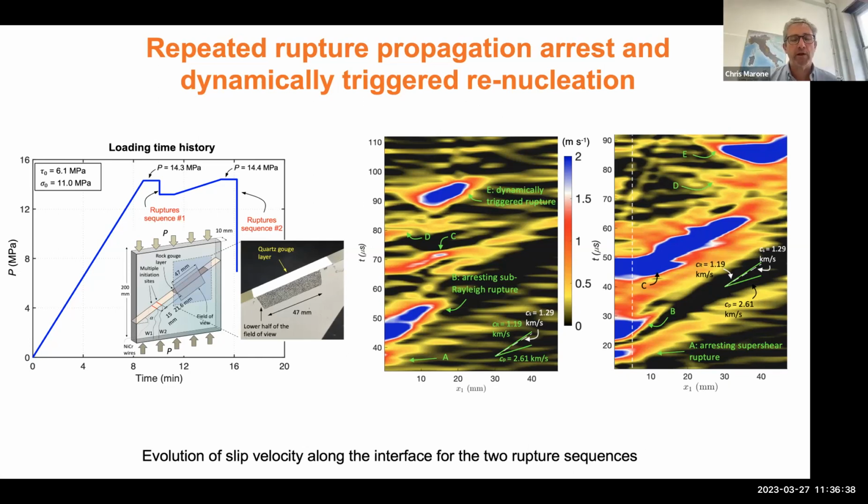Yeah, and maybe that only happens for these more dynamically propagating cases. I don't know, because indeed the dynamic component is a key part in here. If the normal stress does not change rapidly enough, then the shear stress follows, and the Prakash-Clifton evolution does not come into play. So there is an interplay between this length scale and the dynamics of the process.